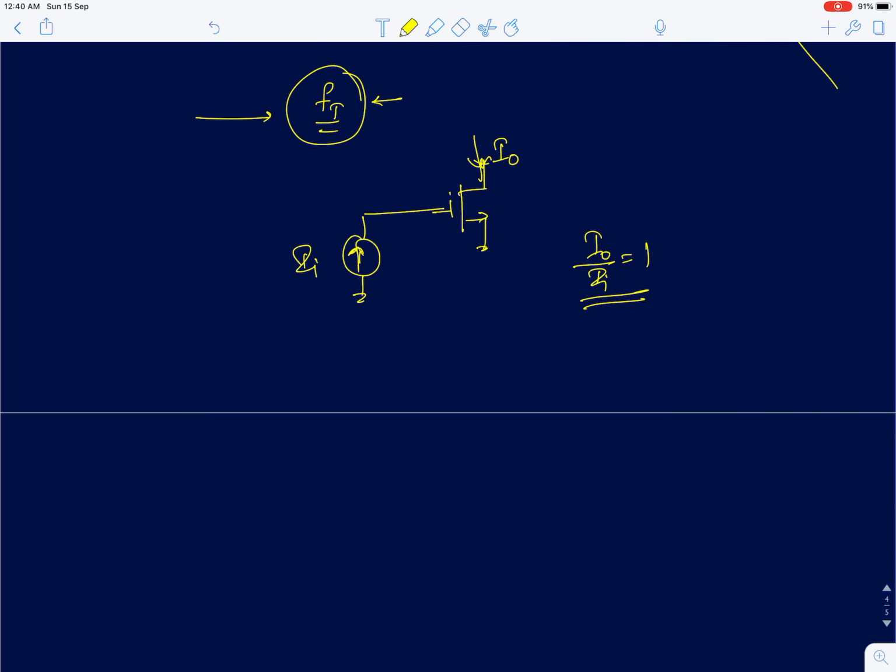For a MOSFET, the output current is always much greater than the input current because an ideal MOSFET doesn't draw any input current. So if the gain becomes less than 1, then it's no longer behaving like an amplifier. There is no power gain. Otherwise, you can also take a single MOSFET and drive another MOSFET with the same, minimum dimensions.